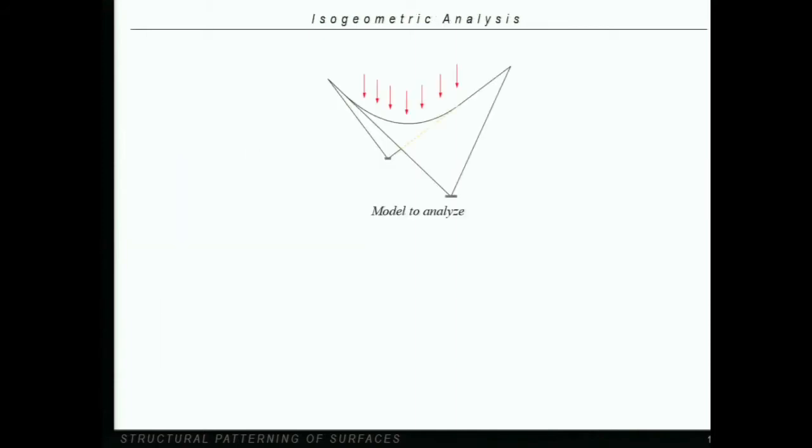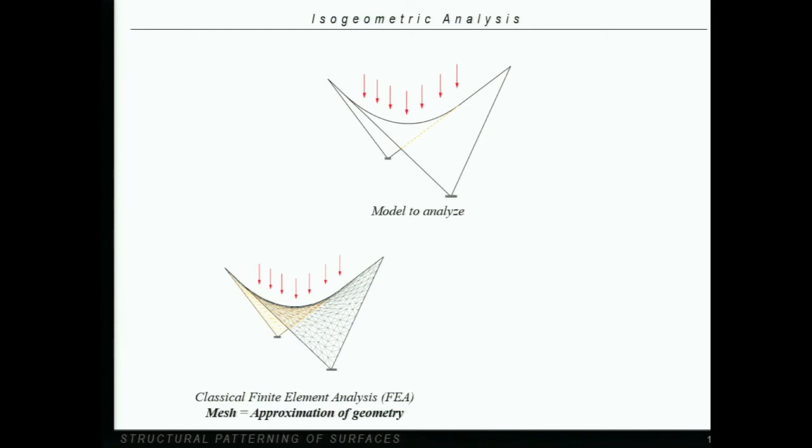Our method is based on recent development in structural analysis that you may know of, which is called isogeometric analysis. While traditional FEA relies on using a meshed approximation of a model geometry, IGA, isogeometric analysis, does not require any form of meshing or further meshing because it relies on a mathematical structure already present in the parameterized surface you're modeling, which really allows for a streamlined modeling workflow between parameter and physical space. And that really justifies its use for the present research.